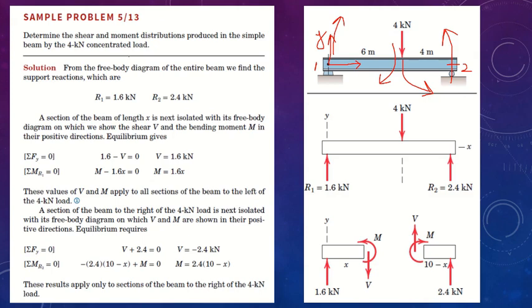The first thing is to fragment your beam. Very simple. Once we have developed the free body diagram and identified the external forces, what we have is the first segment right here on the left side. And we know, for the reaction R1, at any distance, let's say that distance is x, we have an equal and opposite shear force and a corresponding moment acting on the beam.